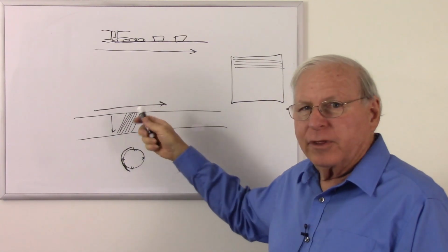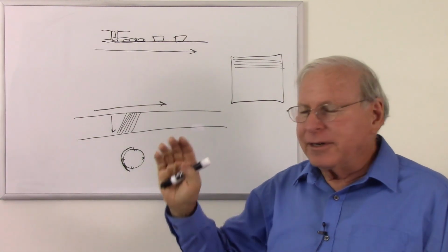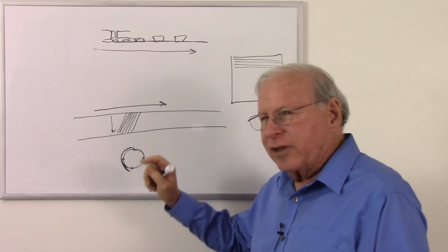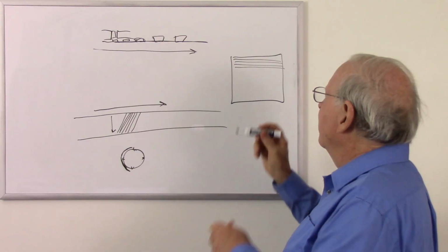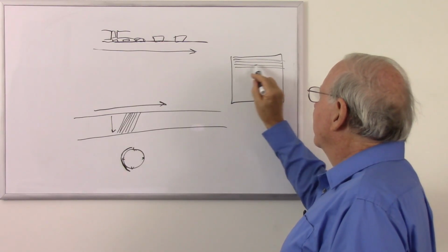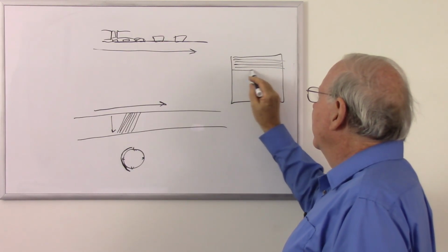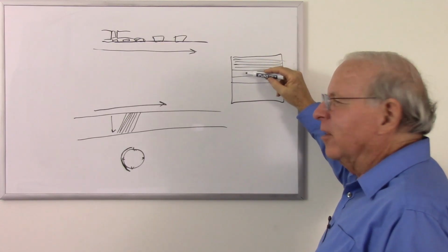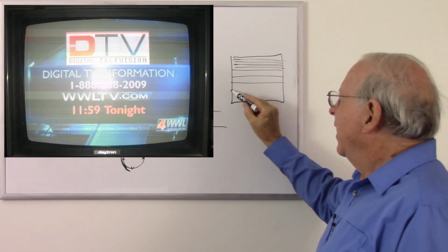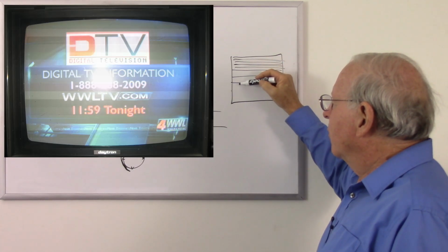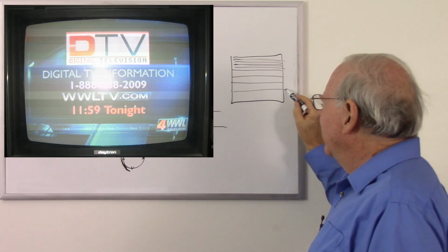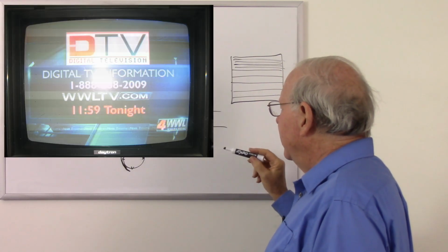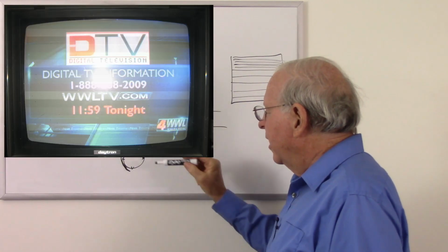And I remember in the days when this was the standard, sometimes if these heads were not exactly clean or were not worn the same way, you would see on the screen slight differences in the appearance in sections. Each 16 lines would be a little lighter, a little darker, colors a little different, and you would see that in a repeated pattern. Every 4th one was the same. And that was a problem that happened with these early systems of scanning the TV lines in a transverse manner.